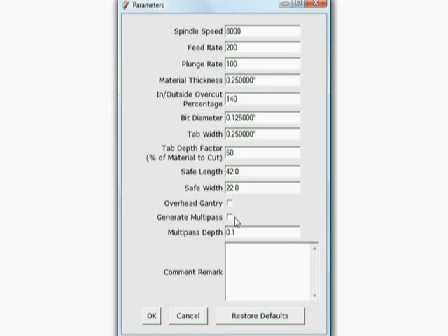And then you say, well, I'm going to burn up a bit or break a bit if I try to drive it through maybe 1/4 inch MDF at that speed. Well, the first thing you'd want to do is adjust your feed rate down to something a little more manageable. When using an 1/8 inch bit or a 1/16 inch bit, I'm running about 40 inches per minute. So I would change that here.